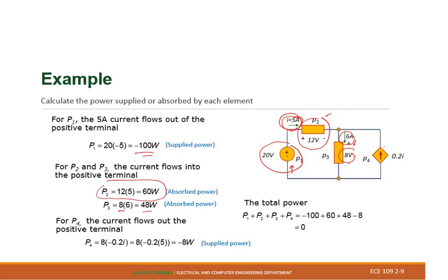If you say I want to find out how much power this supplies here, the current right there, I, will be equal to 0.2 I. I will call it I2 here. So 0.2 times I, which is right there controlled by the current 5, will be equal to 1 ampere. So I can find 1 ampere and I know the voltage, 8 volts entering the negative side here. That's why in this case 1 times 8 is 8 watts supplied here.